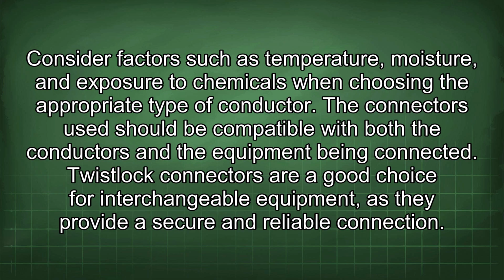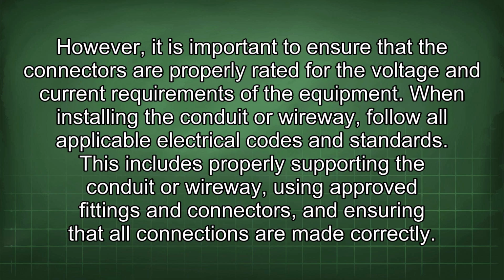Twistlock connectors are a good choice for interchangeable equipment, as they provide a secure and reliable connection. However, it is important to ensure that the connectors are properly rated for the voltage and current requirements of the equipment. When installing the conduit or wireway, follow all applicable electrical codes and standards.